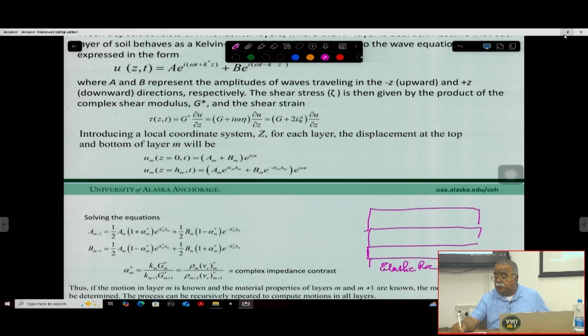We can have a special layer which is the ith layer and the I plus 1th layer, right? So there are two layers, I and I plus 1 layer, and these are all damped soil. And this is our most realistic case, that there is damped soil, a lot of layers are present, and it rests on an elastic bedrock, right?